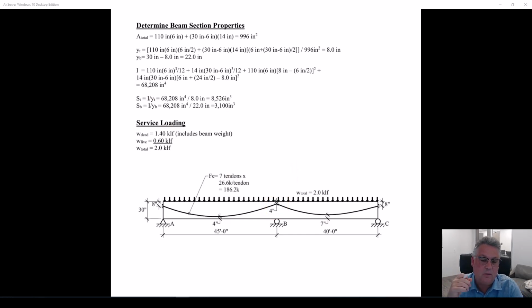Anything less than that, the fact that we have 1.5 inches of cover to stirrups, which we're not showing yet, we'll get to that towards the end of the course, but there are stirrups in there. There's a 1.5-inch cover. And then these 7 tendons are actually grouped. Now they may not be in one group, and they probably won't be, but this would probably be in 2 groups, one of 3, one of 4.